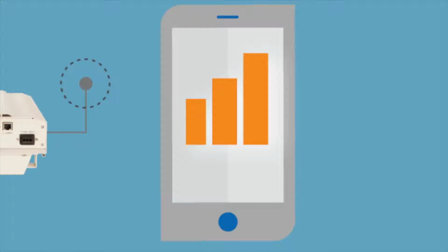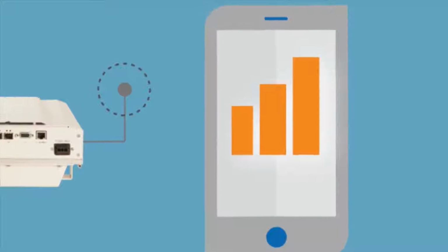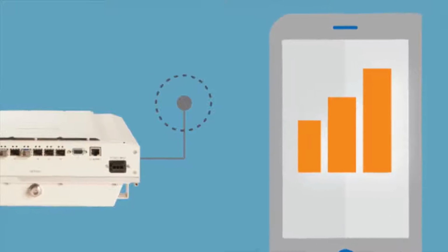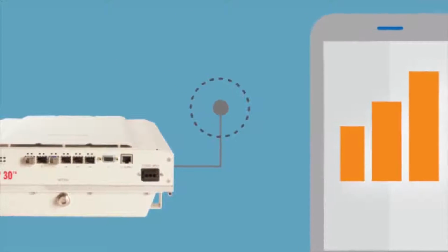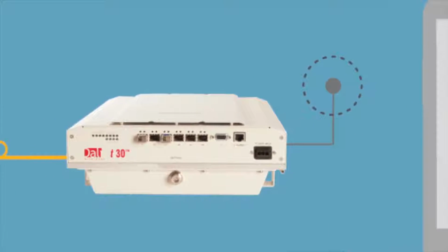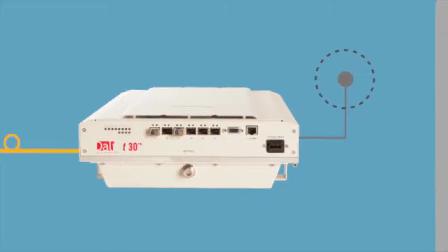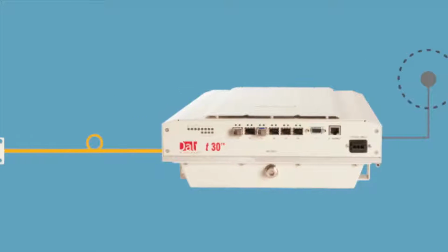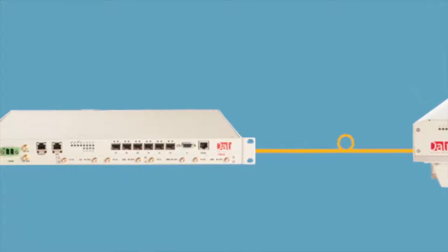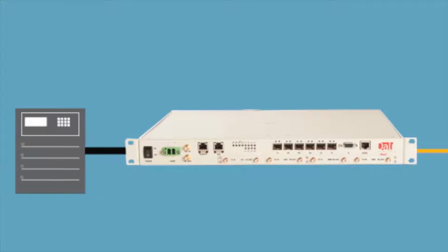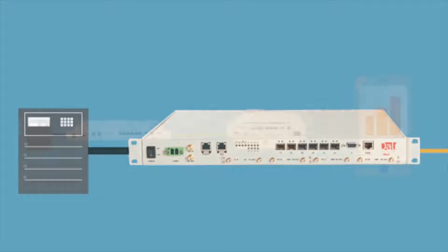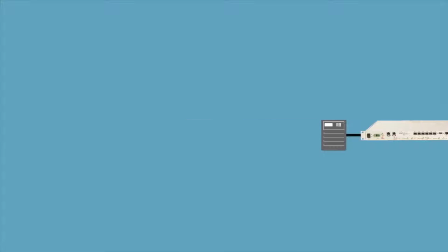On an uplink path, user phone will reply with an RF signal that will be received by antenna, transferred to a remote unit RF input, and then inside the unit translated back to a digital data stream and via fiber optic interface delivered back to the host unit.